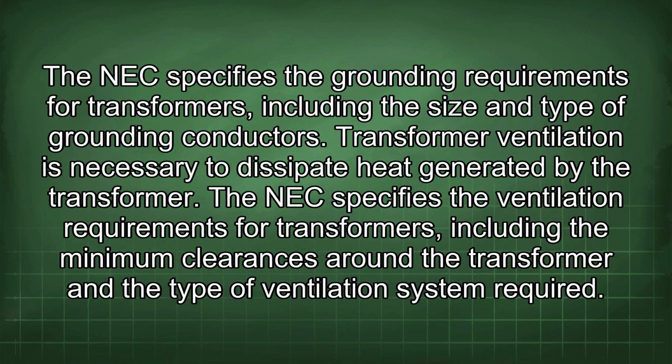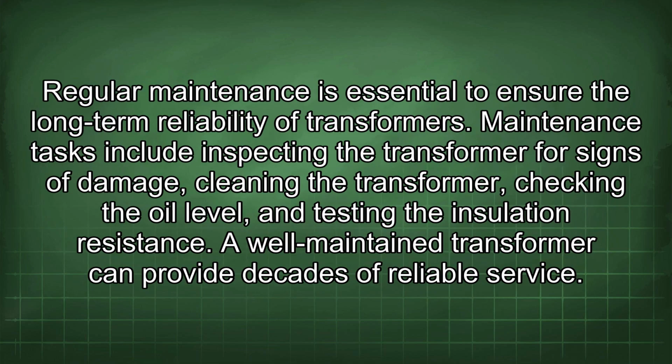The NEC specifies the grounding requirements for transformers, including the size and type of grounding conductors. Transformer ventilation is necessary to dissipate heat generated by the transformer. The NEC specifies the ventilation requirements for transformers, including the minimum clearances around the transformer and the type of ventilation system required. Regular maintenance is essential to ensure the long-term reliability of transformers.